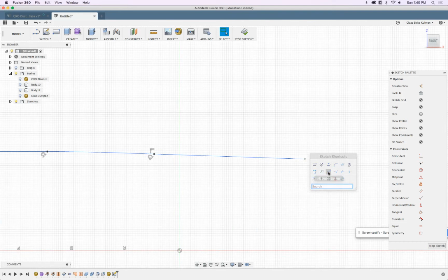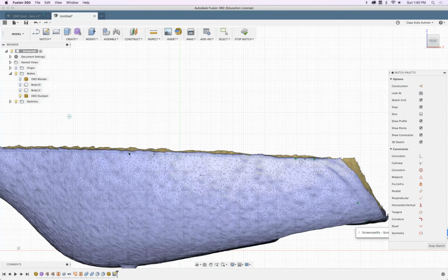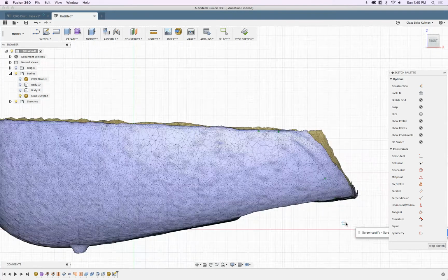Okay. And then here is the rest. Fit point spline, click and drag. The click and drag actually, as you can see, if I now click and I click this, it creates a tangency constraint for me on the fly. Really nice.